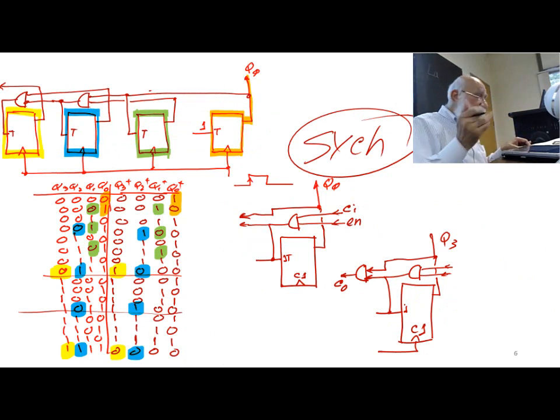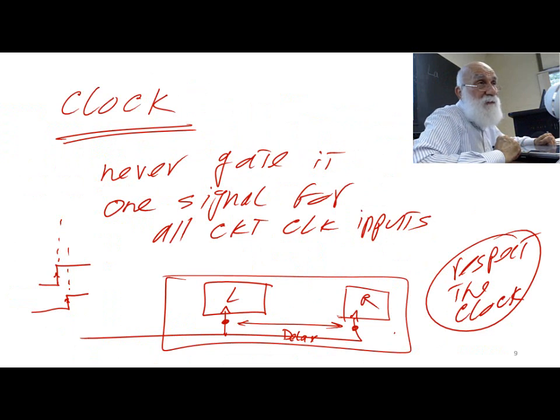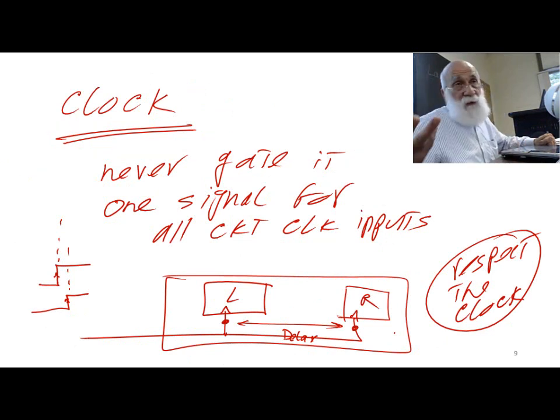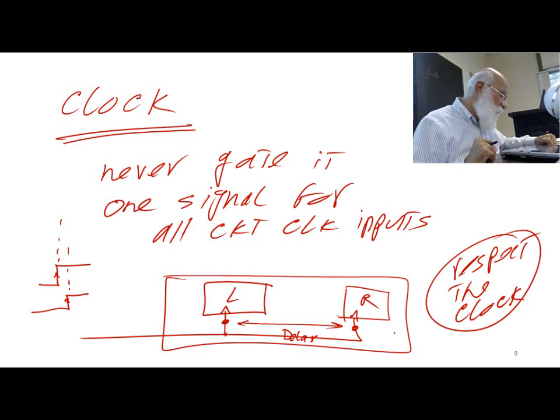Or in the designs that we'll be seeing tomorrow, I'll show you that I do all the designs, all the logic, all the flip-flops. At the very, very end, I say, okay, what kind of flip-flops am I using? Maybe I'm using a flip-flop with set and reset and a clock. And then at the very end, I tie the set, reset, and the clock to the external circuits, and none of those have ever participated in the logic of my design procedure.